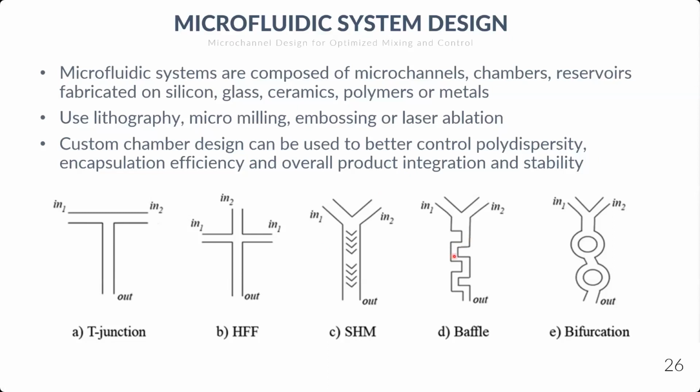So if you were to design a microfluidic channel that offers specific fine tuning and mixing for that polymeric particle, then I think it's definitely worth exploring, mostly because controlling the optimum flow rates, mixing speeds and mixing rates via the proper channel design and proper flow rates can offer you much better control.